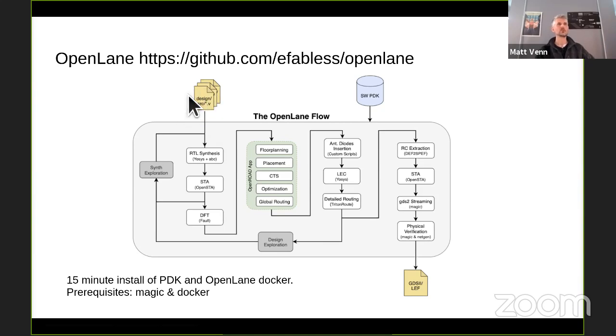So we typically write a model of the thing that we're trying to design with a high-level language. I'll get onto that in a bit. And we need to synthesize that text language into a list of ANDs and ORs and flip-flops, these fundamental digital building blocks.